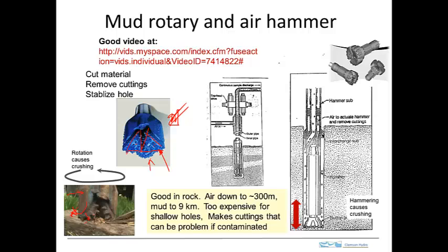Okay, so when that happens, you have something like this. This is the bottom of the hole, and here's this carbide bit, and it rotates down and pushes down on the bottom of the hole. It pushes down with quite a lot of force, and the rock right there is broken. It's crushed. Each time one of these carbide bits pushes down, it crushes a little bit of the rock, and that's how the hole is made. That's how the material is cut. It's cut by crushing.